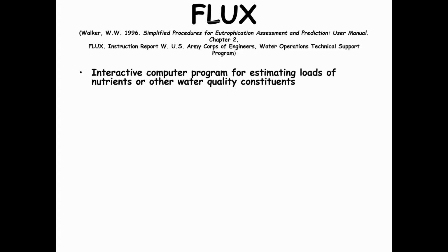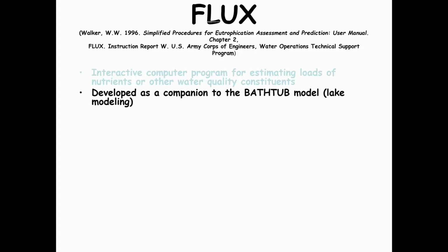The Flux model was developed by the U.S. Army Corps of Engineers and is an interactive program. Basically, it's an Excel spreadsheet program for making estimates of the loads of nutrients or other water quality constituents such as TSS or other constituents of concern.